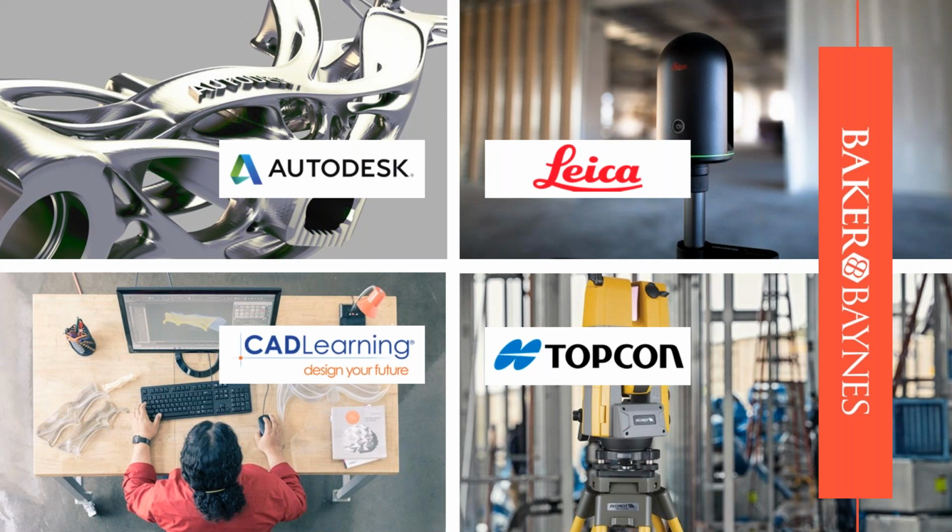And then, of course, for more rugged applications, so civil infrastructure, construction sites, mining, we've got the Topcon GLS 2000. This has a very powerful range. Also, accuracy is really good. Millimeter accuracy can be achieved. You have the starting range that scans up to 150-meter range, which is really long, and of course the higher end, which is 500 meters. So very good capabilities on that part of things. Also a 3D scanner.